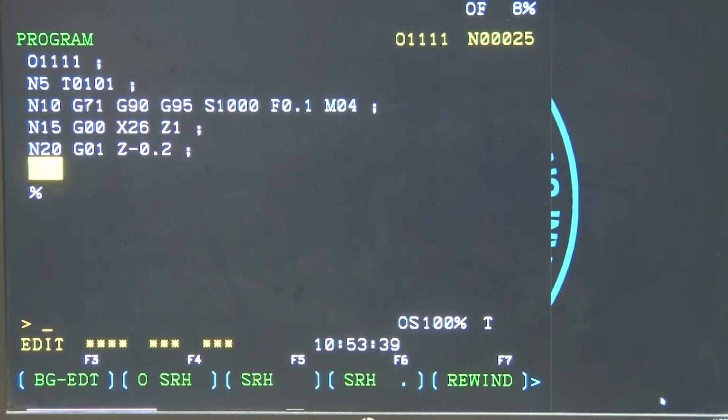Now, G00 is positioning by rapid traverse. We are positioning the tool by rapid traversing, meaning that from the zero position we are coming to a position rapidly, since the tool is not removing any material. G00 tells that this is for positioning the tool, and the traverse will be rapid.